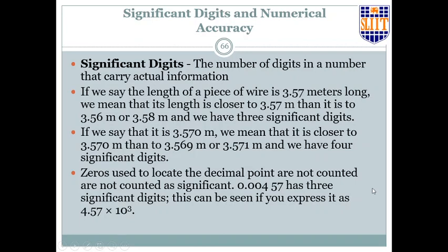Particularly in our case, we will be using digital multimeters. The multimeters you can read, usually it's 1888. Right? 4 digits, the most significant digit is only a 1. So in that case, your numbers would be only 4.